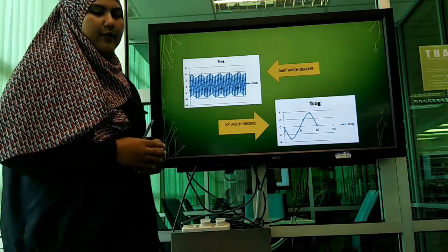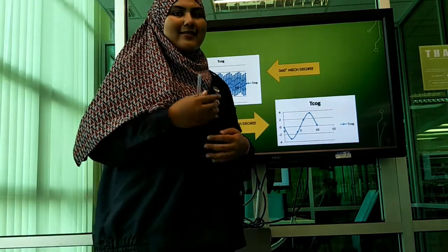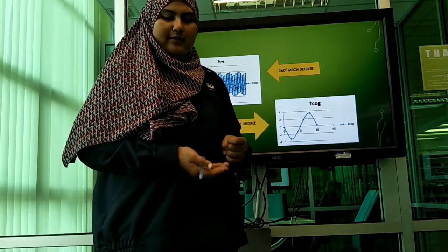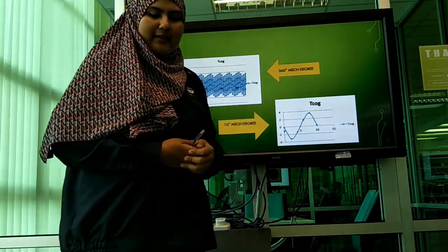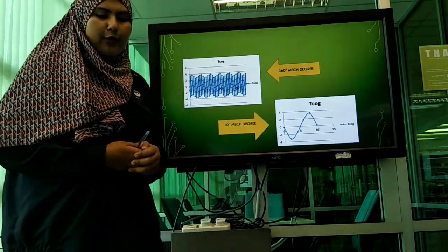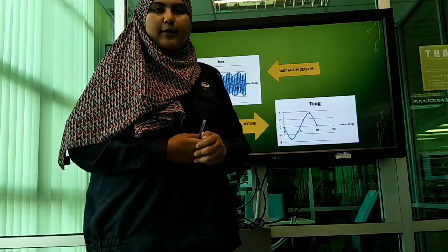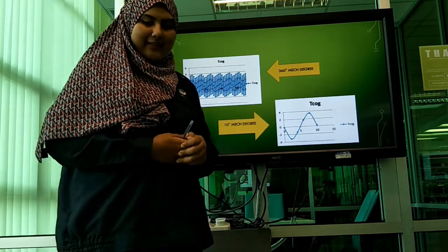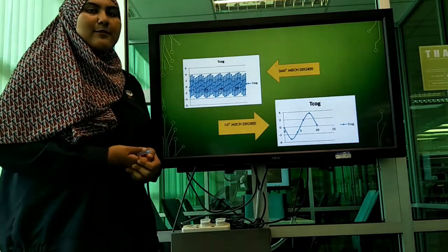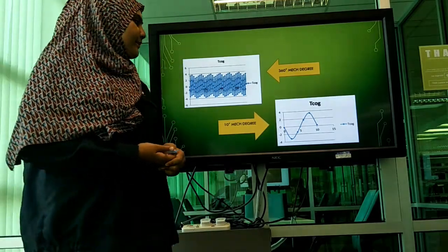The effect of the cogging torque will reduce as the rotational speed increases. This torque is position dependent and periodic per revolution, depending on the number of magnetic poles and the number of teeth of the stator. The highest cogging torque for this motor is 3.5 Newton meter.